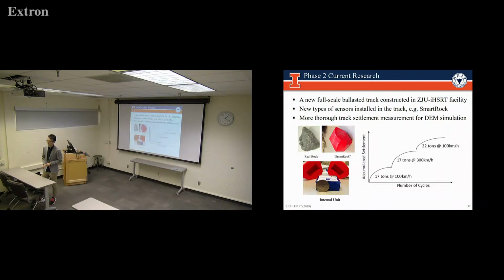The reason I brought GPR is because, especially the moisture, it will have a very distinct frequency component. I mean, this is freely draining material. Don't think about moisture. Of course, all ballast will accumulate moisture and all that. So it's like big stones versus the air. They will have different frequency responses in the signal. If we can isolate different frequency components using some digital signal processing methods, maybe we should have a try, or maybe there's some way that we can work.